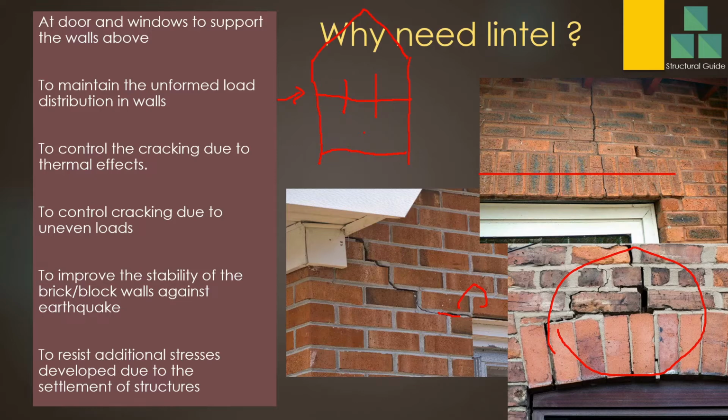In addition, lintels can be very useful in controlling settlement. At the ground floor level we have a tie beam. At the top, if you don't have a lintel, a continuous lintel, not only at the openings, then when there are differential settlements, that could cause issues in the brick walls. If we have a lintel here, it creates confinement, so stress will be distributed, and cracking of the wall will be minimal. They control the cracking. Therefore, lintels are very important, not only to support the openings, but also for other reasons.